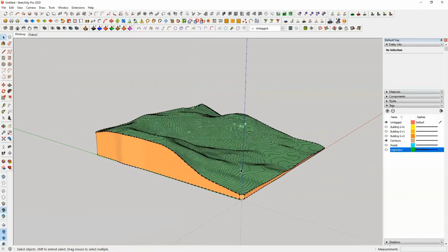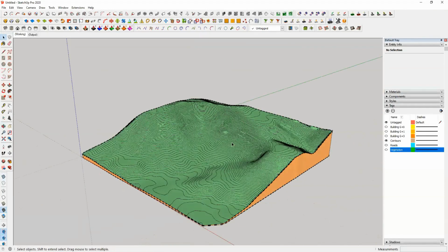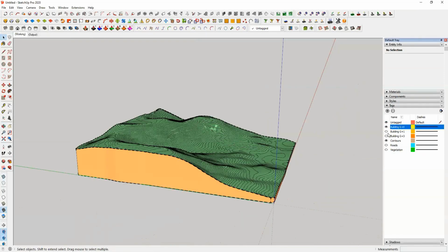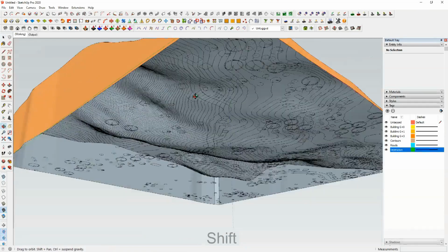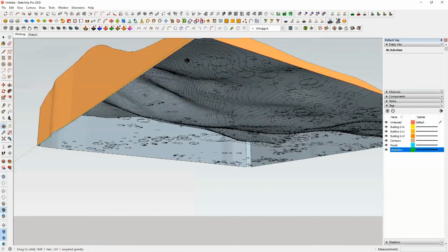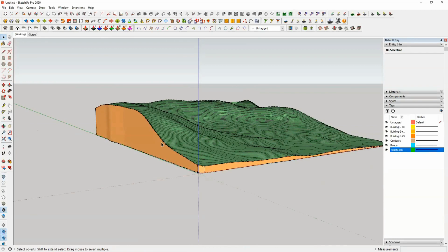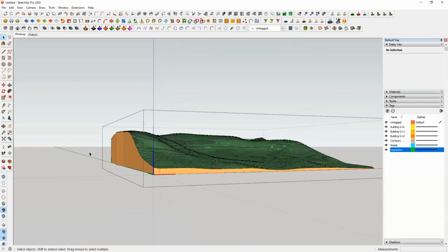So here we have the terrain which we had created yesterday, using the Topo Shaper tool, right? So we have got the other layers as well. So let me turn everything on, and you can see that we have the trees and we have the roads and the buildings as well, all placed at the bottom, right? So let's go inside and bring them all upwards. I'm going to bring them all up because let's turn off the contour.